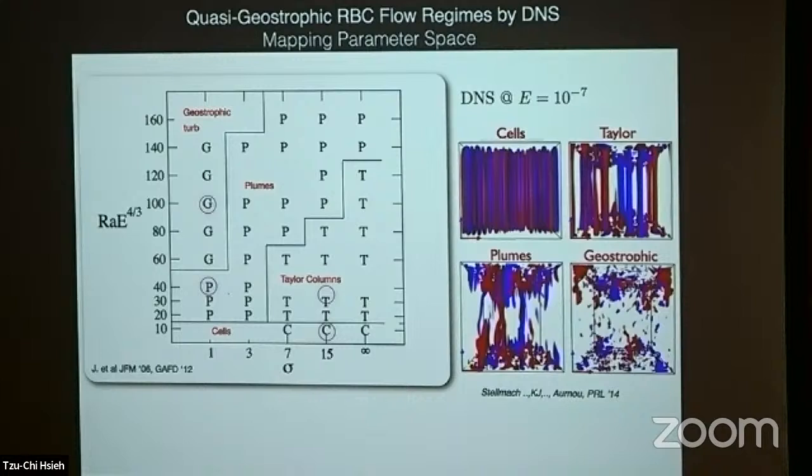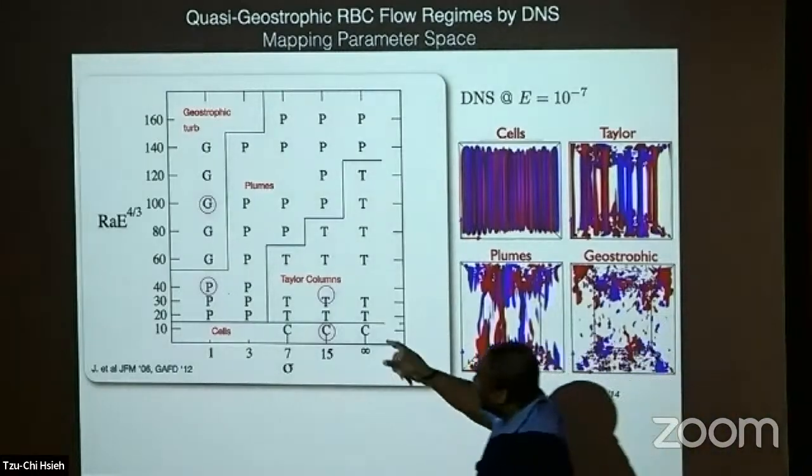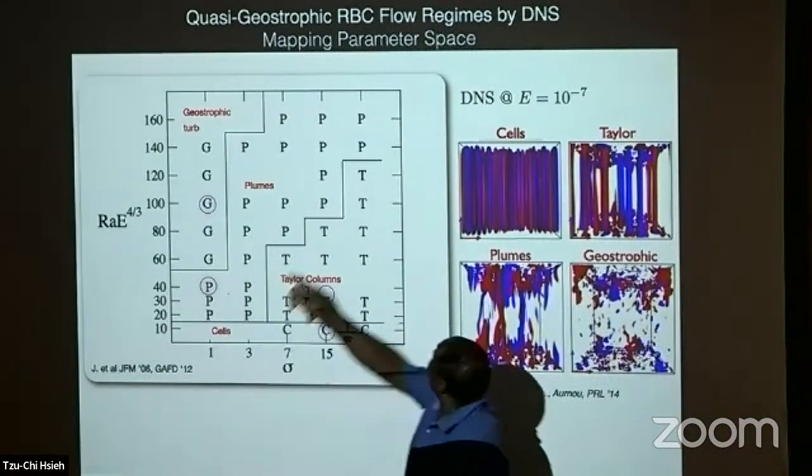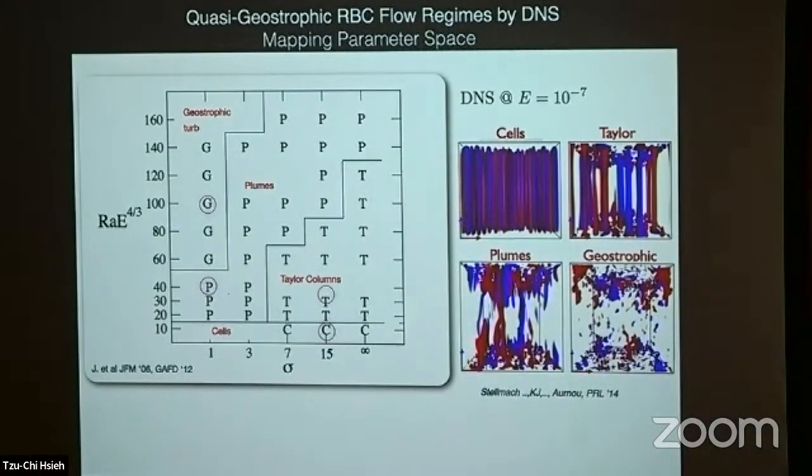We're just looking at the fully blown incompressible Navier-Stokes equations, and we're setting an Ekman number, letting this thing go, and we vary the Taylor number. In collaboration with Stefan Stelmach, we actually used this as a guide. We picked a target reduced rotation number in each one of these regimes, and he got to the lowest Ekman numbers he could at that time. Then pick the Prandtl number, and then go.